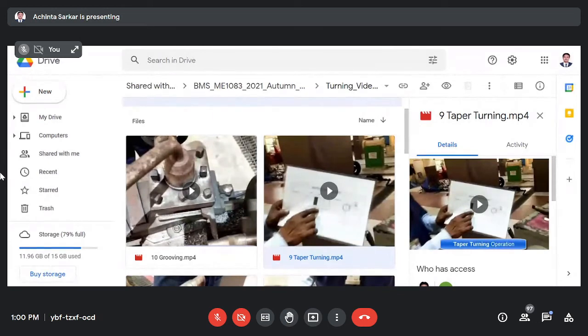Then tan inverse of capital D, the big end diameter, minus small d, divided by 2 into L. L refers to the length of the taper. The taper length may be there in the drawing; without taper length we cannot imagine a taper. So it is the taper length into 2, and that angle we can find out in degrees.